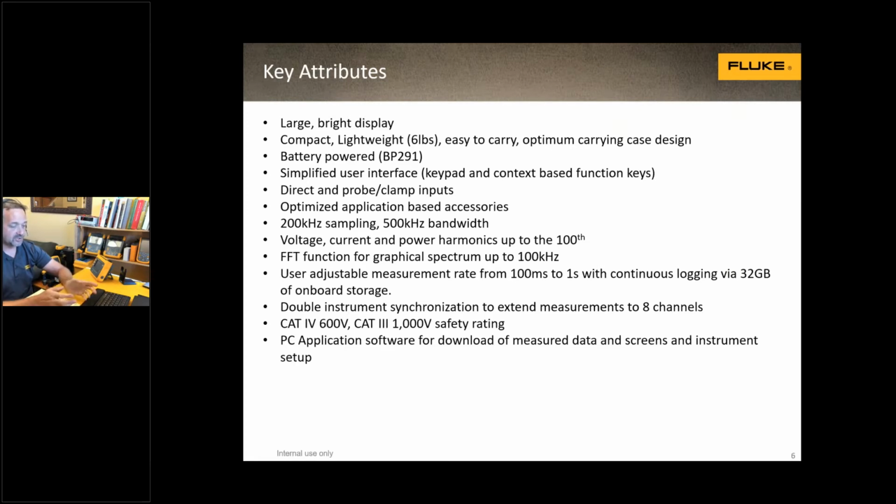It has a substantial amount of internal memory, 32 gigabytes of onboard storage, so you can log data directly into the meter's memory if you want to. One of the other unique features, because you can make efficiency measurements with the meter, is that you can connect two Normas back-to-back and synchronize them. If you take two Normas and connect them back-to-back, you can have up to 8 channels available by connecting two Normas together.